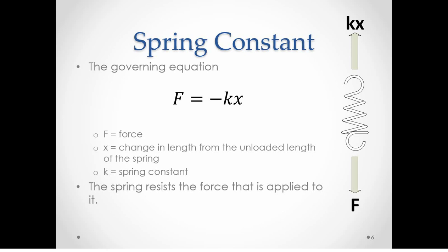One important item of note with this experiment is that you will be measuring the mass of a bucket and rocks that will be suspended from the lower end of the spring. And mass is not force. You will have to perform a calculation on your raw data to determine the value of force that was applied to the spring in each step of the experiment. Well, that one is easy in SI units. Force is equal to the mass times gravitational acceleration, which is 9.8 meters per second squared. In English units, gravitational acceleration is 32.17 feet per second squared.